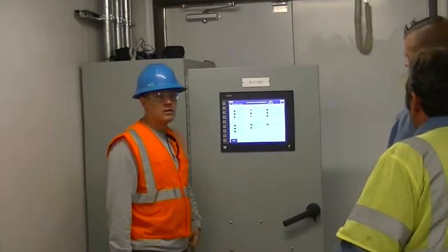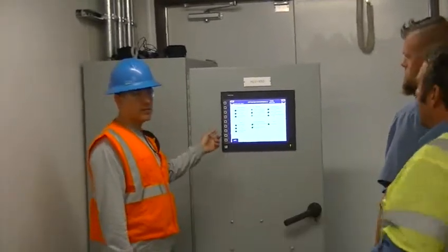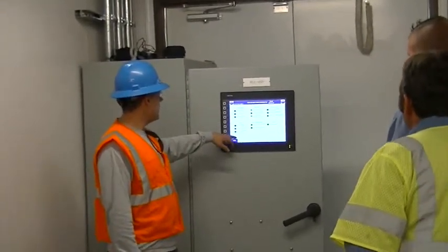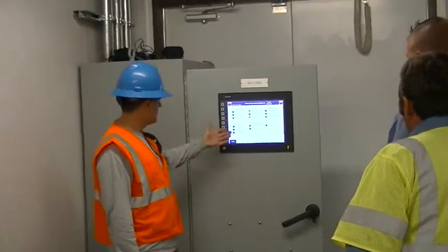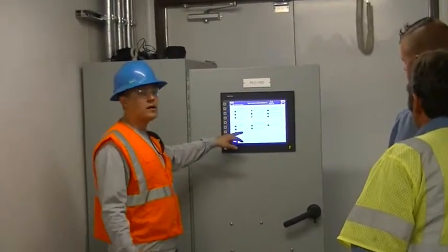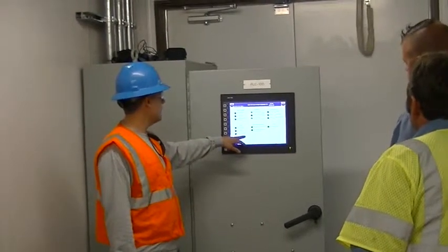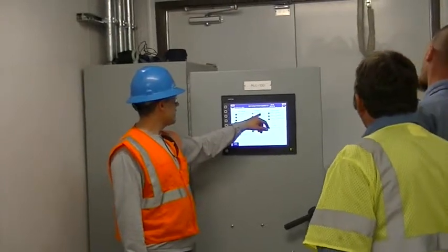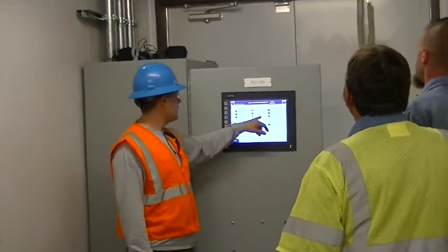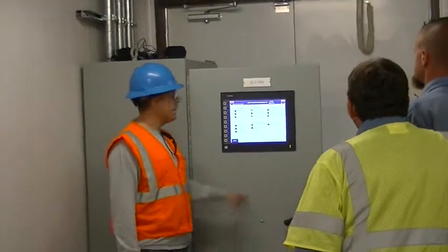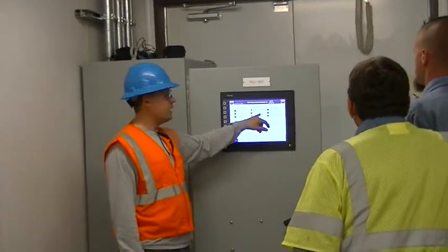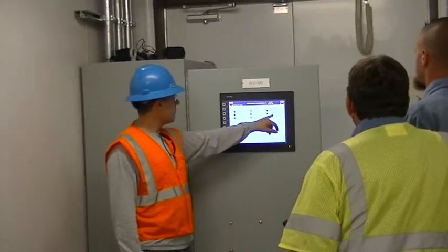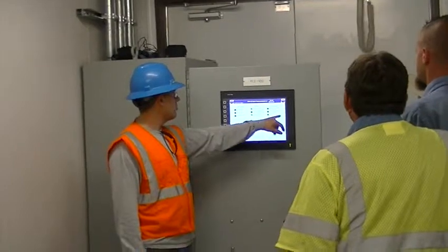Now the power supply, is that in this cabinet or is that in the? This guy. These are the 24-volt DC power supplies that are there. The UPS, you have your on UPS power and your UPS alarm, so that'll come on if you're on UPS power, and then you have your low battery. Right now it's basically in utility position, and utility power is available. And that'll tell you if your generator's on and if the power is available for it. Then you have your generator running, generator engine fail, and generator power available.